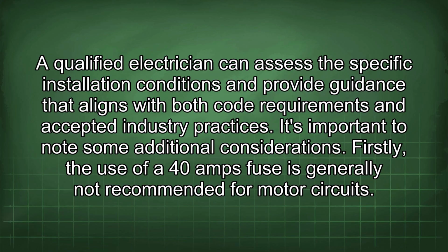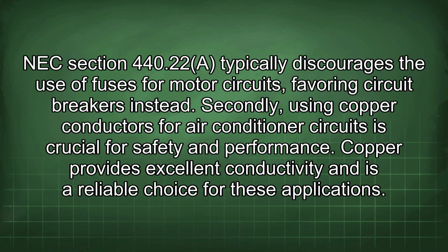It's important to note some additional considerations. Firstly, the use of a 40 amp fuse is generally not recommended for motor circuits. NEC Section 440.22 typically discourages the use of fuses for motor circuits, favoring circuit breakers instead.